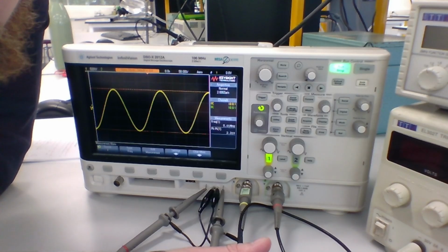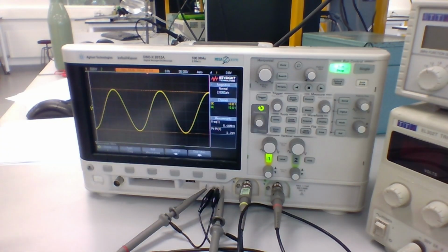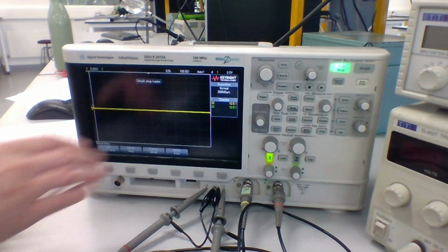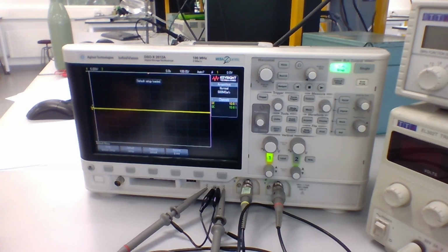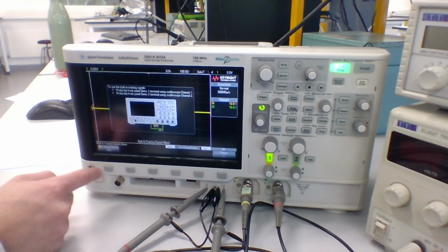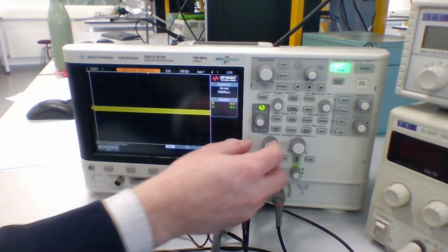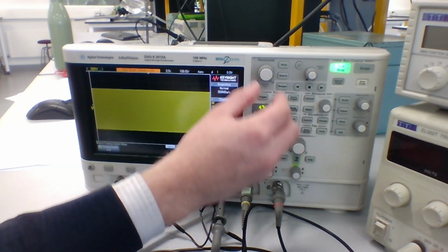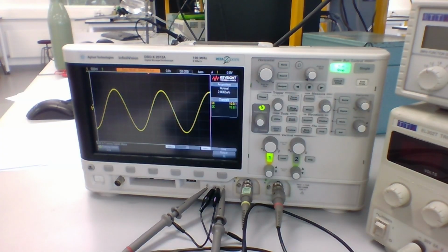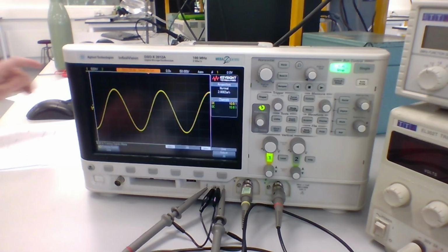Okay. The next thing we're going to do is move on to lab 2 in the manual, and this is about oscilloscope triggering. Following the manual, we're going to reset this oscilloscope. I'm going to press default setup. The probe setup is still the same as before. Again, we're going to turn the sine wave training signal on using the same procedure as before and scale channel 1 to be able to measure that signal. There we go, so we're seeing the same voltage scale and time base.